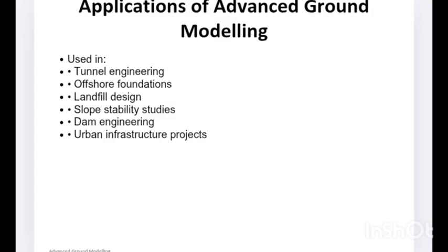Landfill design. Ground models assess permeability, contaminant migration, and stability, and all of these are necessary. I remember in one of our discussions in the group, we talked about the fact that when you want to site a landfill, you're looking for a place with very low permeability.